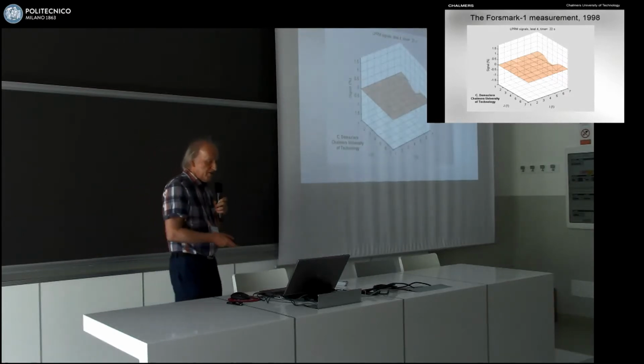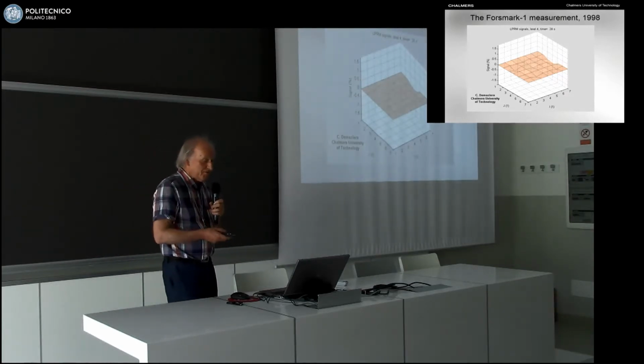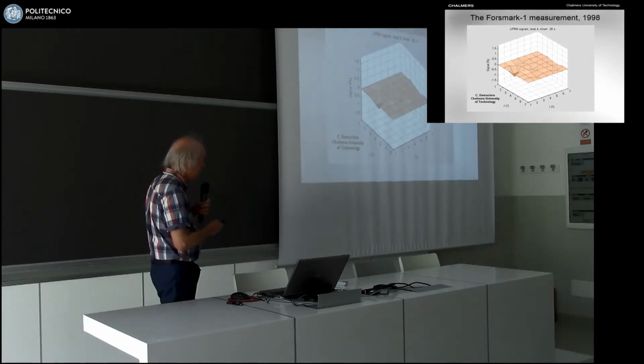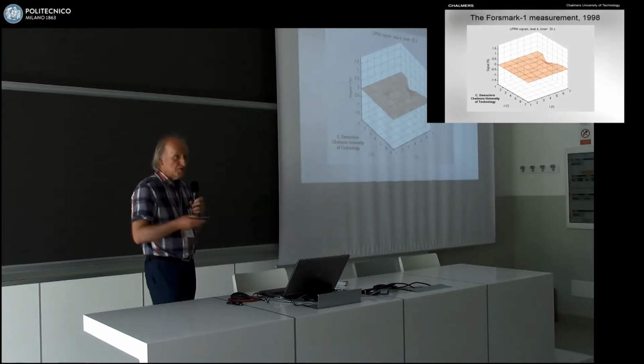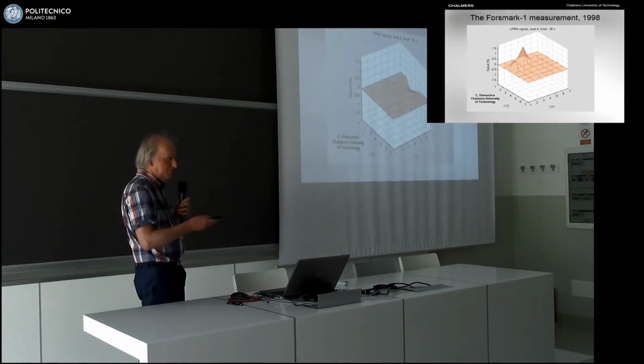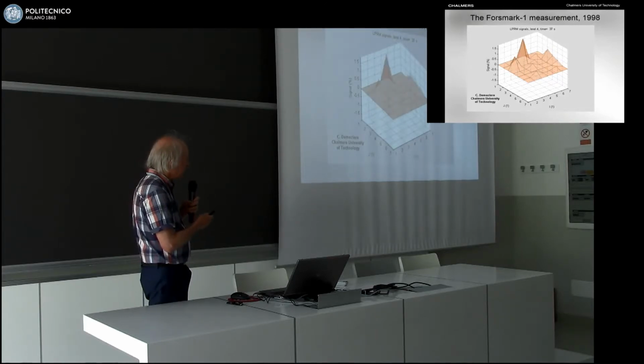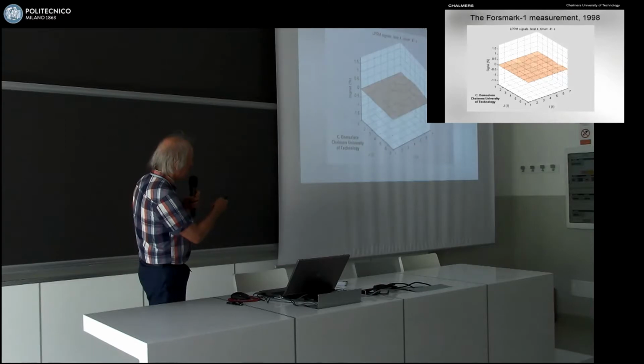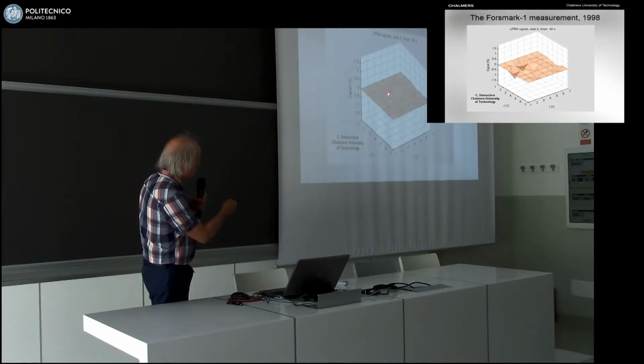Now we have a measurement here which shows that reality is always not as nice and smooth as in the models, and that's the measurement from which one has to find out where the fuel assembly is that is unseated. And from this it's not so easy to find out. It's intermittent, some detectors did not work, so the point which doesn't move here is not because there is no change.